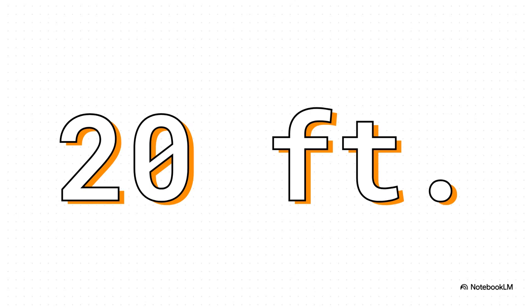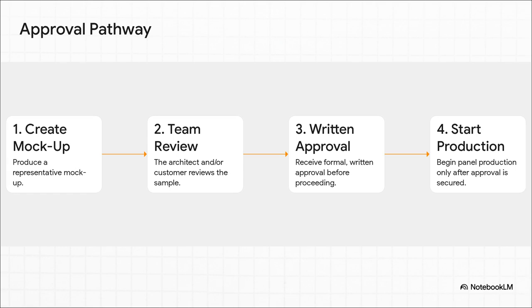Now, this is one of my favorite little details in the standard, a 20-foot viewing distance. Why? Well, it's actually pretty smart. It forces everybody to look at the finish from a realistic perspective, the way it's going to be seen on the actual building. You're not supposed to be judging it with a magnifying glass, where tiny acceptable variations can look like huge problems. So here's the path to getting it done, and it is a strict sequence. You create the mock-up, the design team reviews it, you get that formal written approval, and only after you have that piece of paper in hand can mass production begin. You can't skip a step.